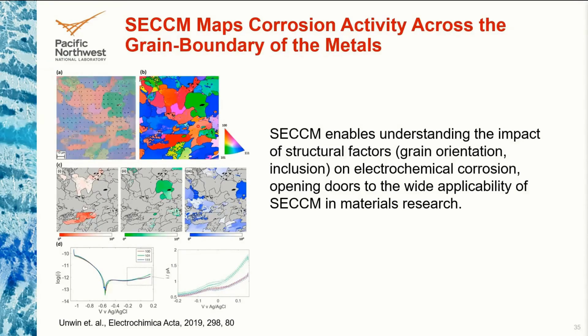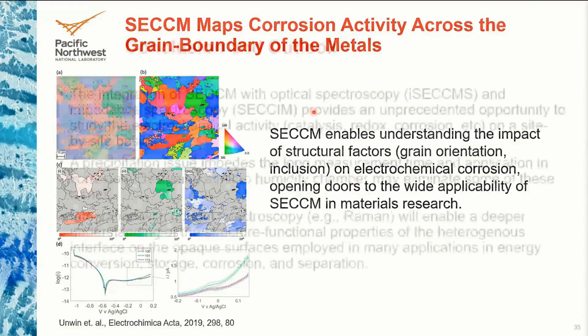That is very important for corrosion applications. For example, whenever an alloy formation occurs, or when you prepare the corrosion metal for alloys, the different islands and precipitates that form on the surface exhibit different corrosion behavior. Sometimes they can also act as a starting point for corrosion.